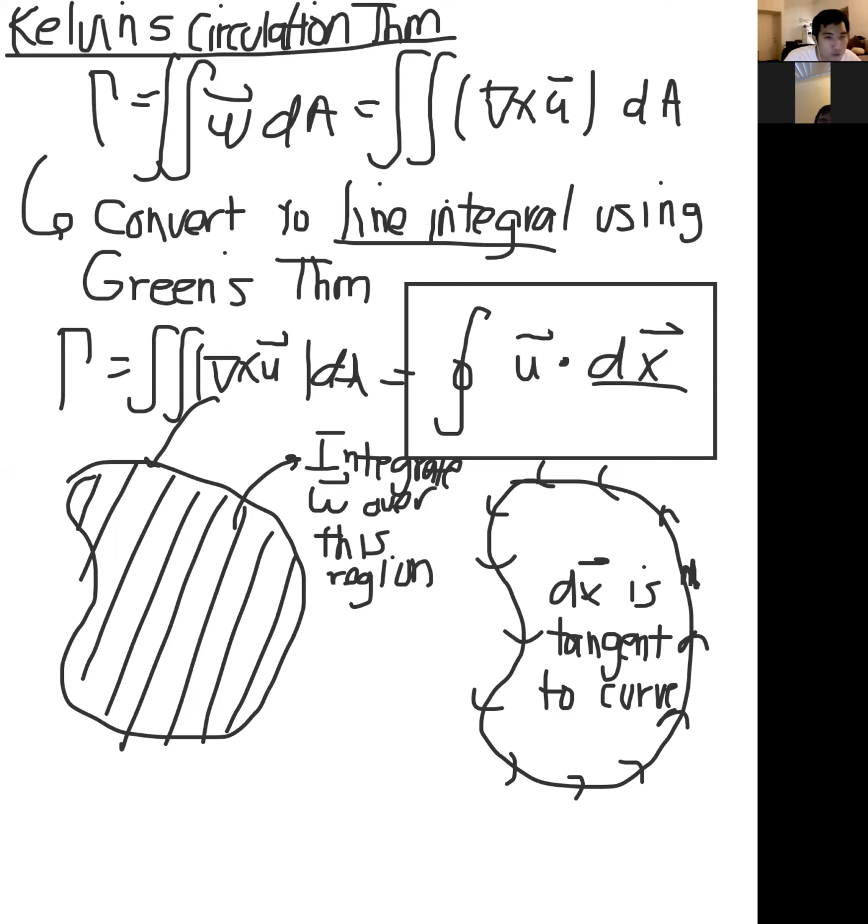Intuitively, the reason that these two are equivalent is that on the left, since we're integrating the vorticity over the area, another way to think of the integral is that it's a summation operation. We're adding up all the tiny contributions of vorticity over this entire area. And that's equivalent to the right scenario because we're integrating the velocity as its dot product, as it aligns with this closed curve that goes around our surface.